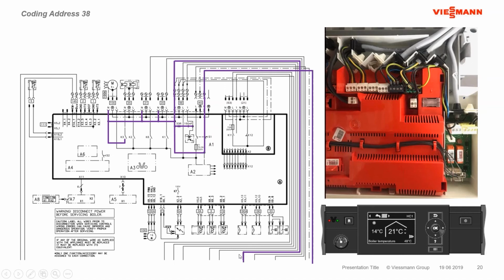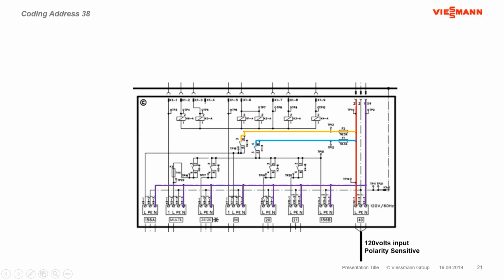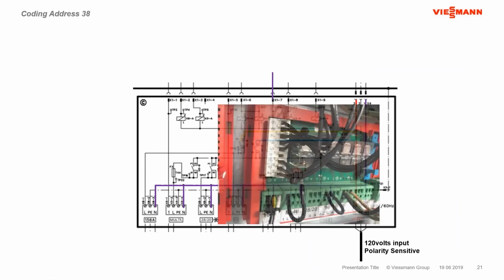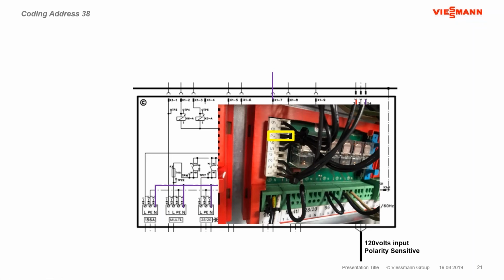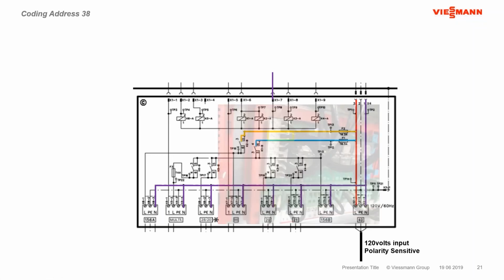So we're back down here at the control, from the control console back to the pump module, and that neutral sits at X1-7. So we're wiring right here to the X1-7, and that basically ties the neutrals on your relay coils. So all those coils, the neutrals are powered. As soon as we push the power button, the neutral is sitting right there ready for that contact to be completed. So that's just on the push of the button.